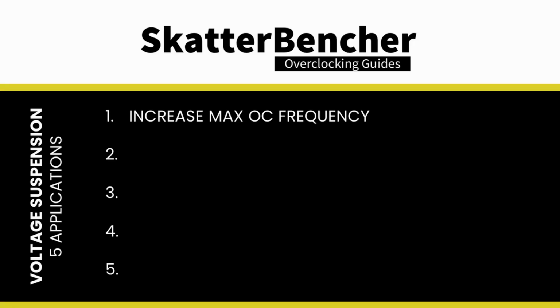I found 5 situations where voltage suspension can be useful in helping you get more stable and higher overclocks. First, the obvious one. When you increase the PBO frequency using the reference clock, you will need higher voltages to ensure stability. You can use a higher ceiling voltage to have a higher voltage than Precision Boost requests.